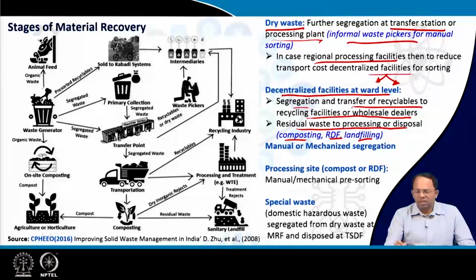So that means if I have a mixed waste stream, I will first take out the recyclables. Whatever remains, I will then separate into the organic part and the inorganic part, and the inorganic part will go to RDF. Whatever cannot go to RDF, that is, whichever has calorific value less than 1500, will go to the landfill sites along with the inert material. And all this processing could be done manually or via mechanized means.